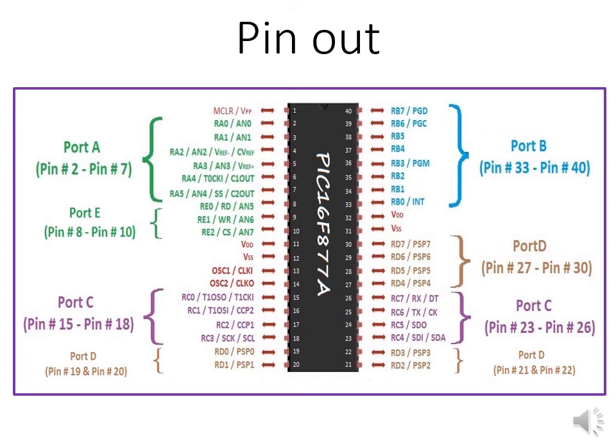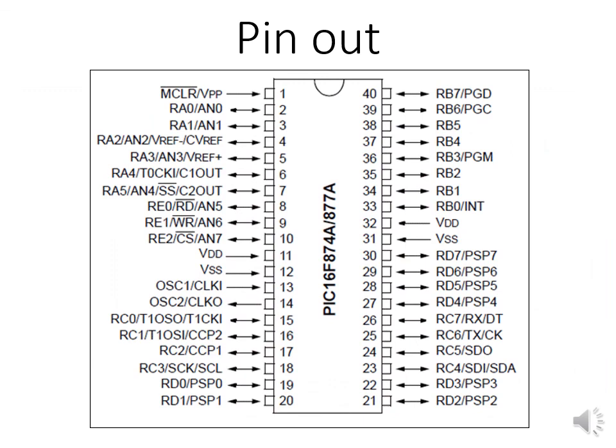Here is the pinout for the PDIP, that is the dual inline package. It's a 40-pin package. The core function of the bulk of the pins is as digital input-output pins. However, as can be observed there, most of the pins have more than one function. So each pin generally has a number of multiplexed functions. The function of a pin will depend on what is connected to the pin, as well as the program that has been written to run the microcontroller application.